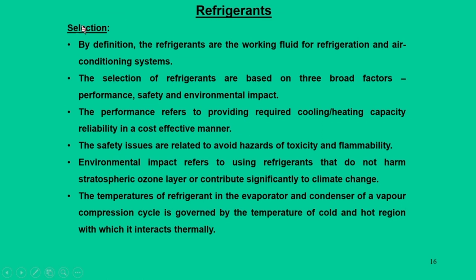And when you choose a refrigerant, the temperature of the refrigerant in the evaporator and the condenser for a vapor cycle is mainly governed by the temperature of the cold region and hot region with which the system interacts thermally.